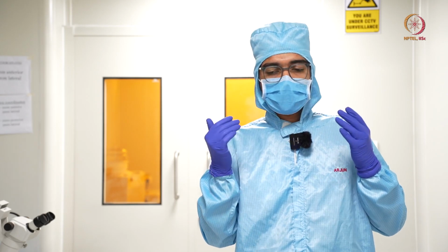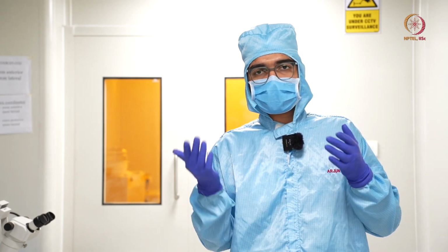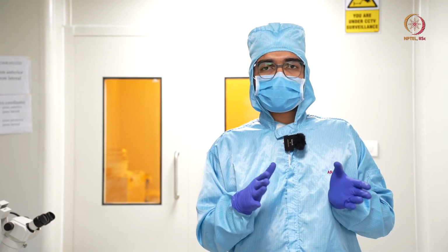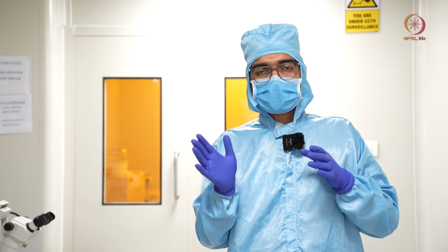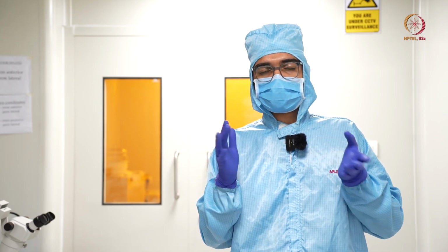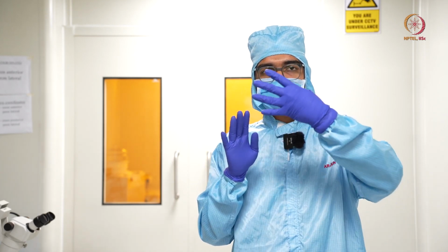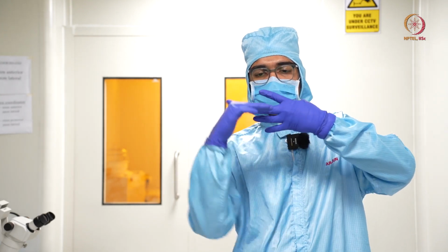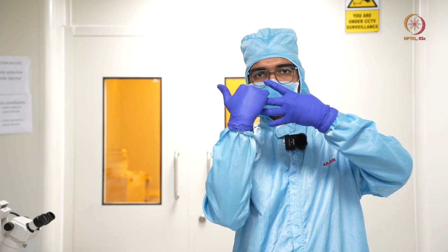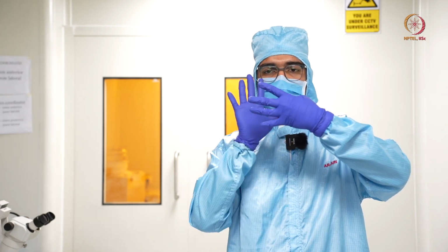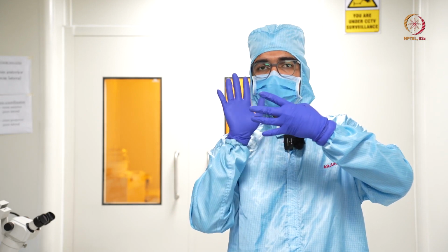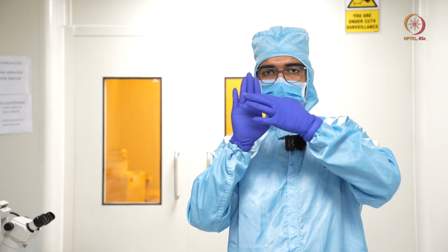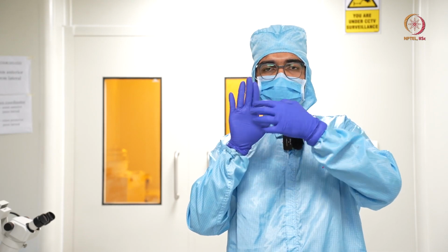Now as I said, the photoresist might have different properties. They are mostly classified into positive photoresist and negative photoresist. Now, when I say positive photoresist, what it means is that, say, these fingers are the mask, so this is the opaque region, and this is the transparent region, right? The light can pass through here, the light cannot pass through there, and I have the substrate here with the photoresist, which is positive.